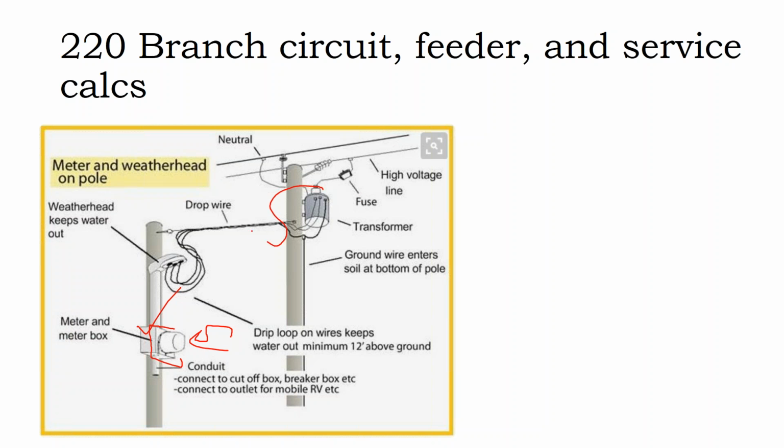If you have an overhead wire run, the same issues with leaks and moisture. The utility doesn't want moisture getting into their meter, and so what might look a little ugly to someone, why are these power lines just dangling off of here, and it looks like there's a lot of slack in them going into here? Well, this is called a drip loop, so water can drip off the cable rather than running directly into the cable. And that applies on a rooftop too.